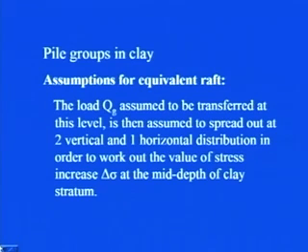As you have seen in the shallow foundation chapter, how you were calculating the settlement below any footing or foundation system. Usually what we see is that when the raft has been placed at that particular depth, the load will get transferred to the soil lying beneath it. So, it gets transferred in a 2 vertical and 1 horizontal system.